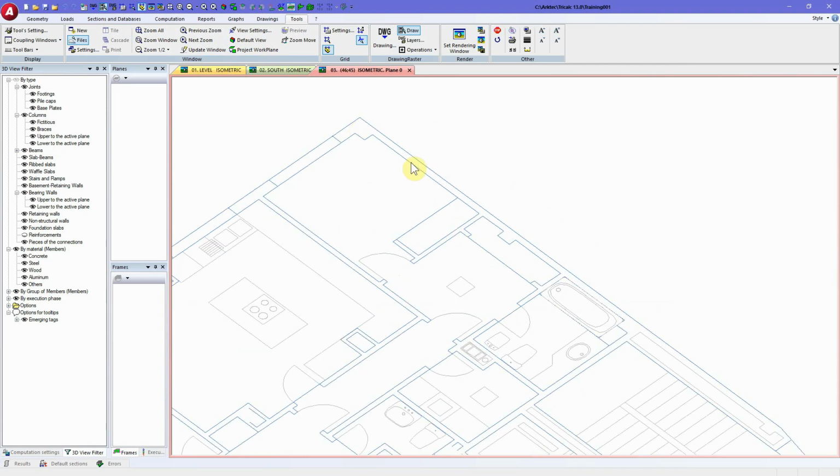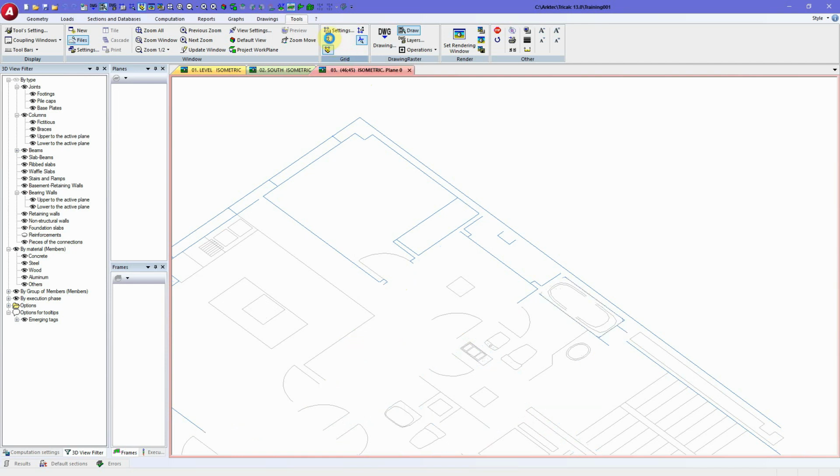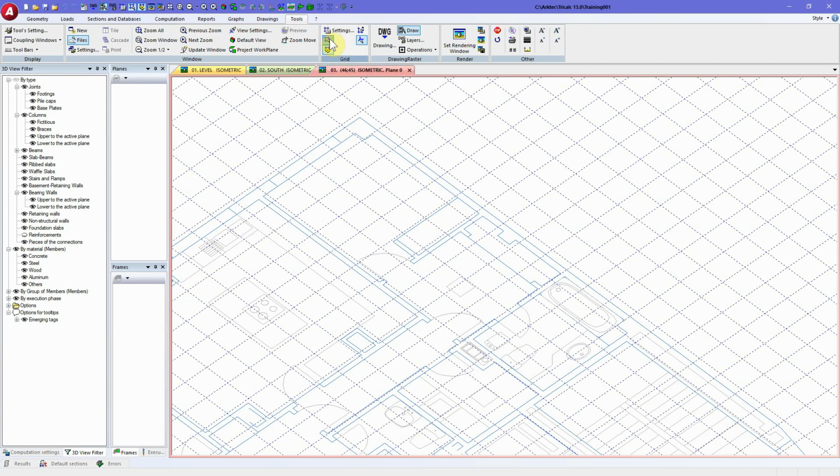To create LSF panels here, LSF frames, you can start by defining any reference point that you would like to use. To help you, you can use also the settings for the grid. You can change the settings. Let's say I want to use a grid line with 60 centimeters of visual spacing and the mouse spacing for 5 centimeters. I'm going to draw lines for this grid. So this grid can be activated or deactivated at any time.